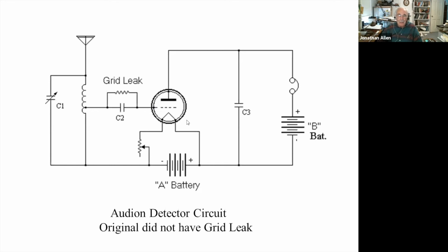There was something on the order of 1 millimeter of mercury, or a tenth of a millimeter of mercury pressure of residual gas in the tube. And as a result, the electrons trying to find their way from the filament to the plate would bump into gas molecules, ionize them, and you get an ion flow in this direction and an electron flow in this direction, and the two are bumping into each other, and it just wasn't happy at all.